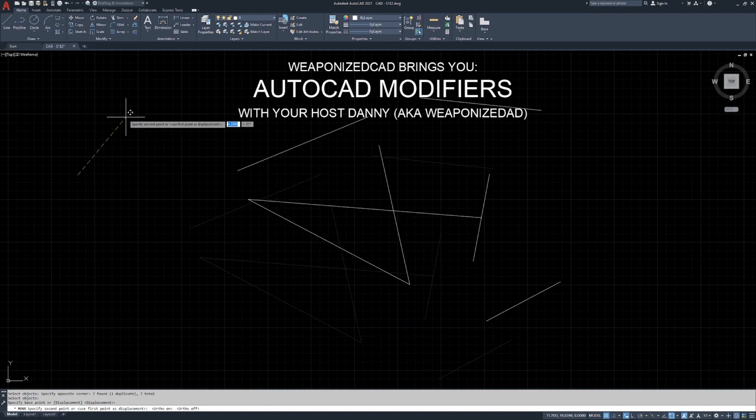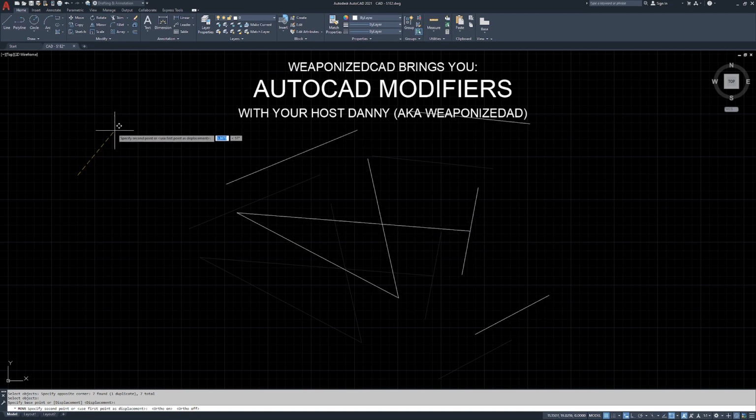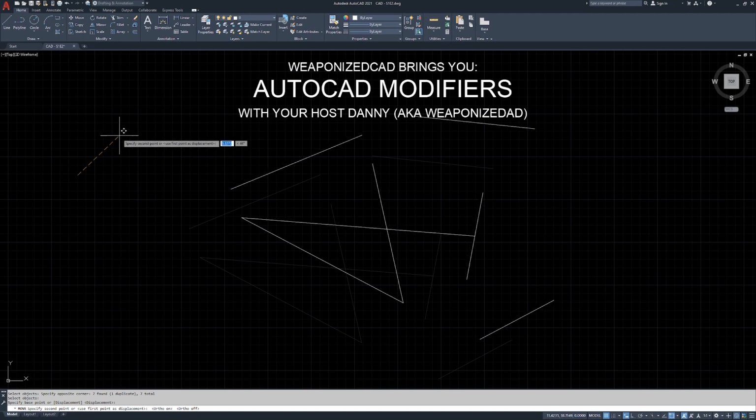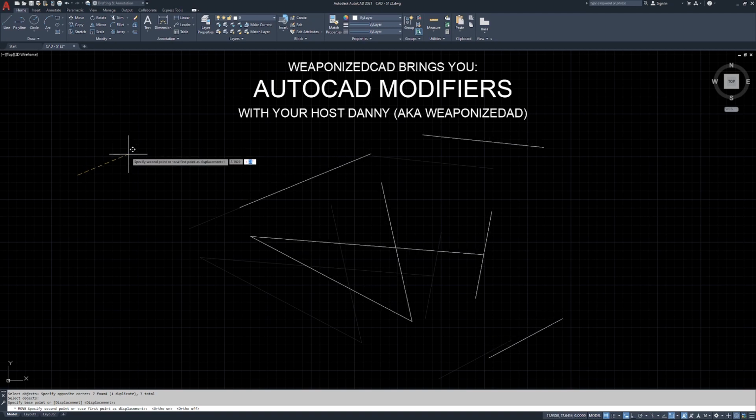Otherwise, it's going to move it in whatever direction the cursor is pointing. And it gives you that dashed orange line. And that's telling you the direction that it's going, but it's not giving you the angle in an obvious place. It's off the side of the cursor, and unfortunately I can't move my cursor over to show you, but if you actually hit the tab button, you notice that where it says specify second point or use first point as displacement, it says 3.1629, and then next to it is less than 23 degrees.